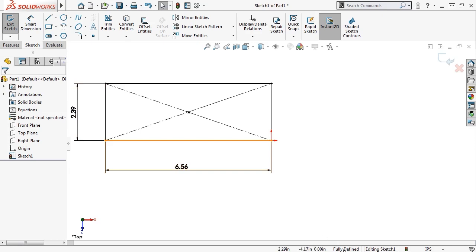When creating sketches in Solidworks, you don't have to fully define sketches. This is a nice feature because oftentimes, especially in the early stages of design, you may not know what dimensions you will be using, but you have a general idea as to the shape. Having said that, it's generally considered good practice to fully define sketches once you finalize a design, so that when you go to manufacturing, you know that there are no arbitrary values defining your part. The sketch color coding is a very easy way to identify sketches that are or are not fully defined.